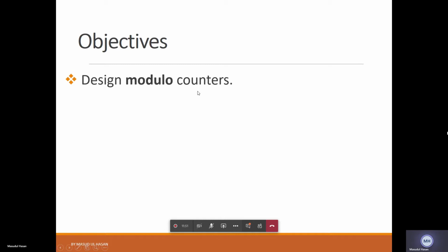Yes, you are correct, but there is a small change. It will be called mod 6 counter, but it will count up to 5, from 0 to 5. Right? In that sense, you are correct. So it will be from 0 to 5, meaning 6 different values. So that will be mod 6 counter. And what you will do, you will change it here. Just this change.